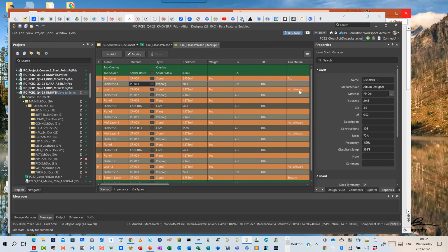It's all about materials. And part of it we're going to discuss here in just a moment, which is, first off, cores versus prepregs. You always have to alternate. The prepregs are the glue sheets that glue the various different layers together. The cores just have the copper on both sides. So if you have a core here, you must have at least one prepreg sheet here before you have another core. From a manufacturing standpoint, next week in materials and the week after in manufacturing, we'll go into that in more detail. From an electrical performance point of view, though, from a signal integrity standpoint, creating our controlled impedance stackups,